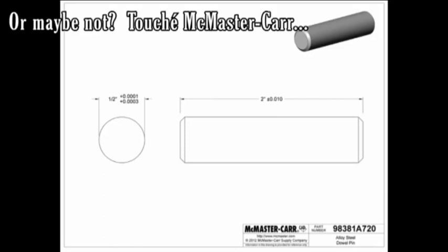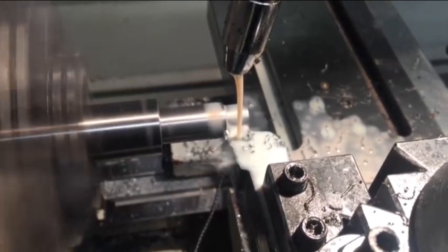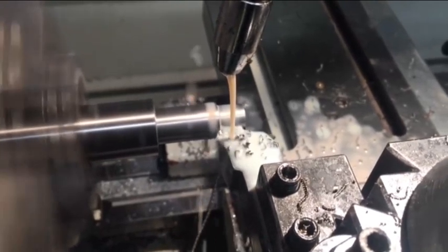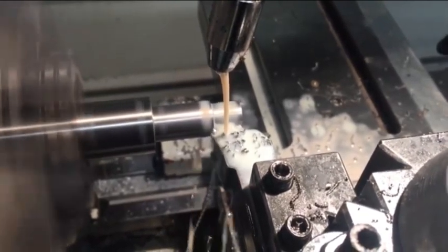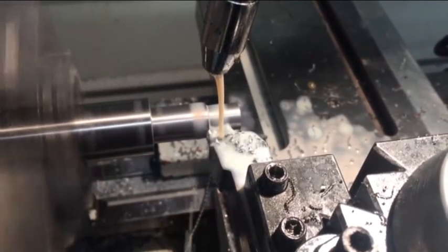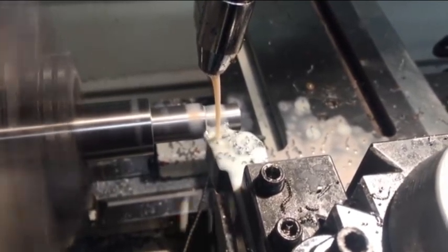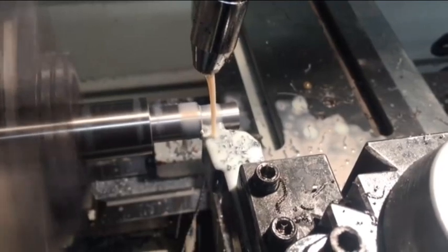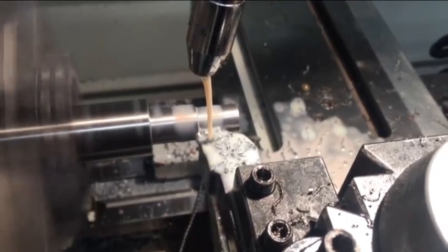So instead, you can just say the tolerance will always be a bit over the specified dimension, where a bit over scales roughly proportionally to the target size. We could say that all the pins will be between 0.1 and 0.3% larger than the nominal dimension. The problem is we don't want people to have to constantly calculate what these percentages are. The system we use instead is called the ISO 286-2 standard.